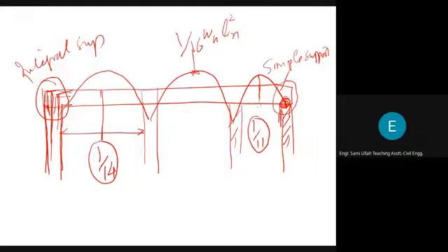Okay, so the difference of positive bending moment for the exterior span is due to the exterior supporting system. If the exterior support is integral, then the value will be 1 over 14. If the exterior support is simple, the value will be 1 over 11. And for all interior spans, the positive bending moment value will be 1 over 16. I hope this is clear.